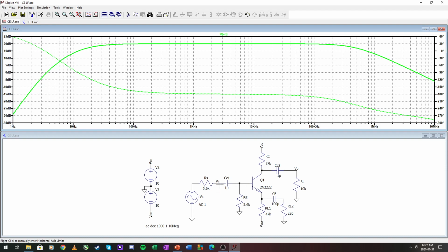Just remember, if they are too large, they need to charge up in the beginning, and your circuit will be a bit slow to increase its gain on the output side. It will look kind of funky, and if you use electrolytics here, yeah, your output can start to look kind of strange. Just keeping that in mind. Okay, on to our next example.